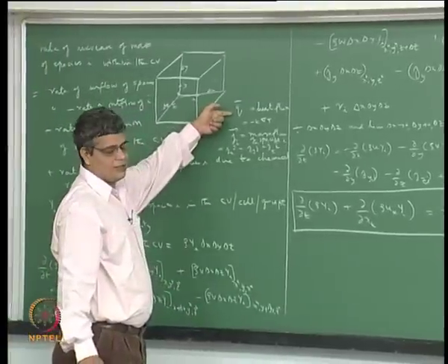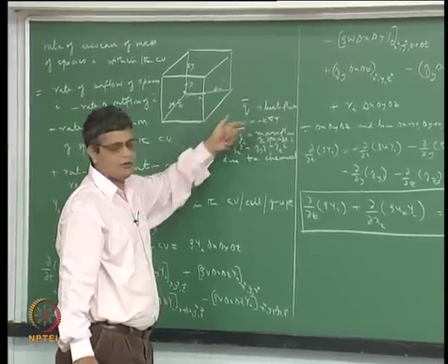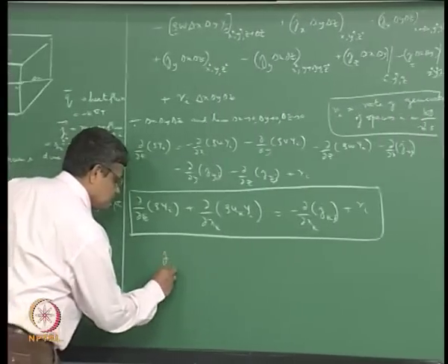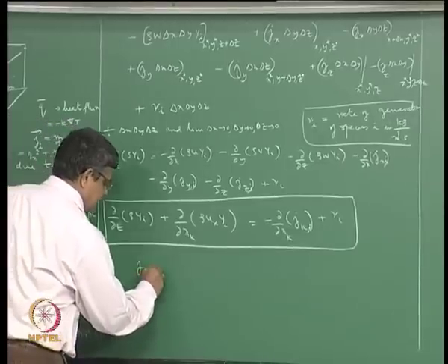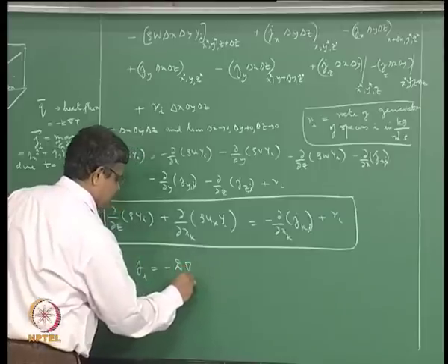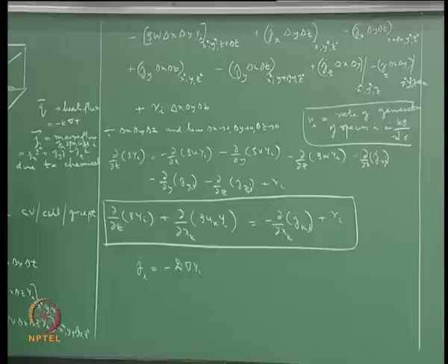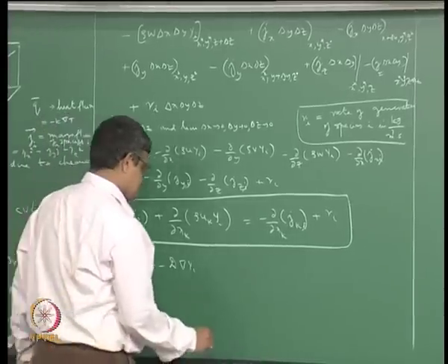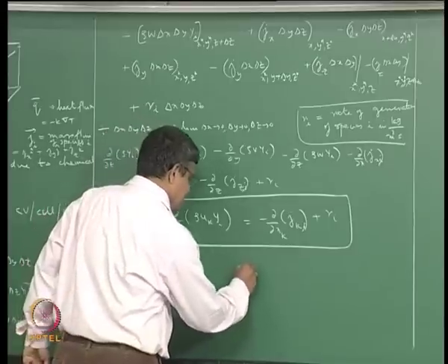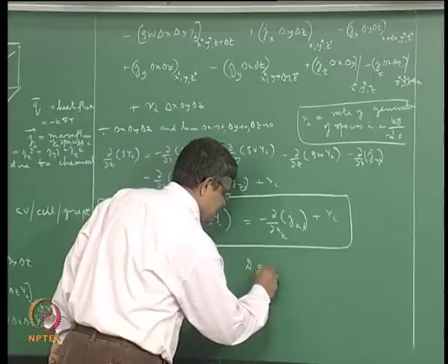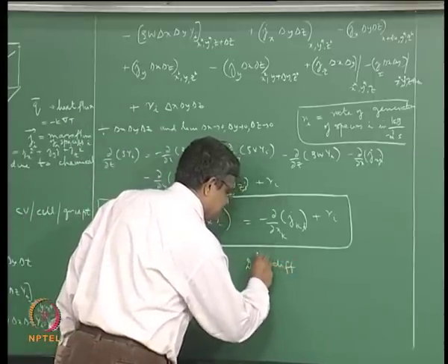As we have done in the case of heat flux, where we invoked Fourier's law of heat conduction, we can also describe the mass flux through Fick's law of diffusion. So Ji is minus d times the gradient of yi. We have to be consistent here dimensionally. Here d we have to be very careful about; this is the mass diffusivity.